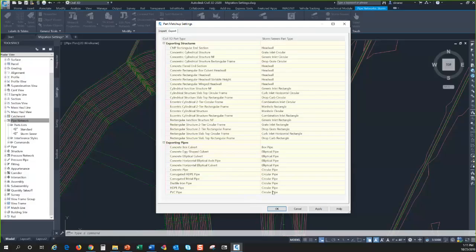Storm sewers doesn't look at that as a visual entity like it is in Civil 3D, where you're laying it out and you want to have a visual representation of it. Storm sewers is only interested in the hydraulics and hydrology. So it views a pipe as simply a conduit with certain properties that get punched into hydraulic calculations. So that Manning's N value is really the only thing that's critical.